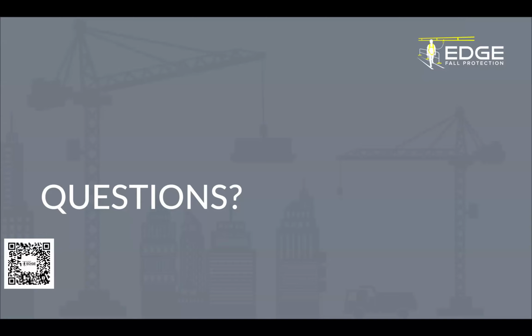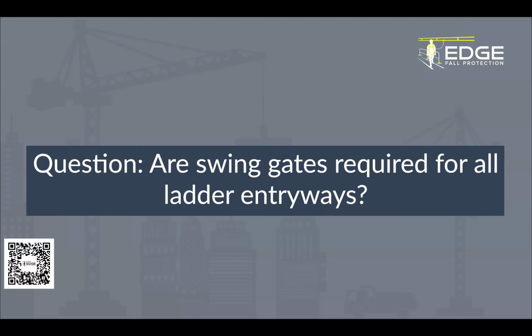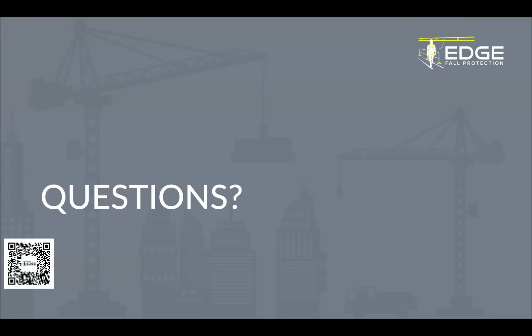Great. The next one here is, are swing gates required for all ladder entryways? Yeah, another good question. It's an opening, it's a hole, it's an opportunity for you to fall through. So yes, a self-closing safety gate should be provided at any sort of ladder transitions where a person is exposed to a fall.